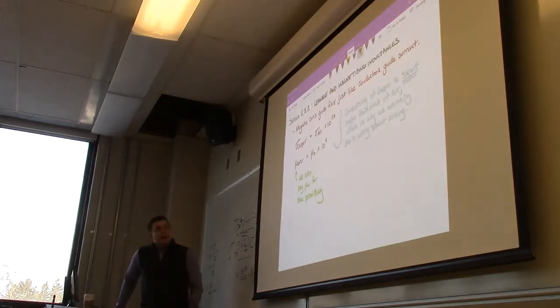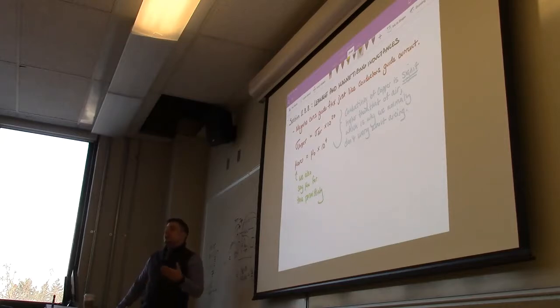So what you see is that the permittivity of the core is not as high relatively when compared to air, to free space. So this is the reason why leakage inductance is much more of a concern than leakage current, right? Any current that would be flowing through the air. For electric circuits, it's not even a consideration unless you're doing some really high voltage, very specific calculation. You would not consider that at all. But for magnetic circuits, because the difference is not as stark, we do have to consider it.